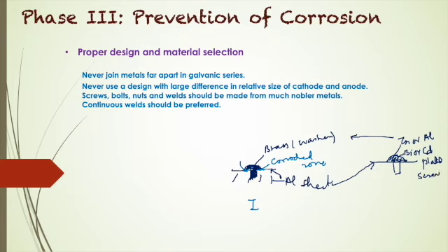So the washer is made up of zinc or aluminium, and the screw is plated with cadmium or bismuth. Out of these two selections, this is my selection number 2. The first selection is actually a poor selection. Why? Because it will lead to a higher rate of corrosion, whereas this will fall into my good selection. Okay, so the selection of material also plays its role.